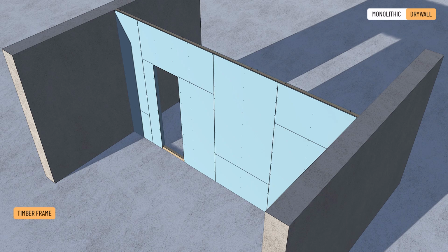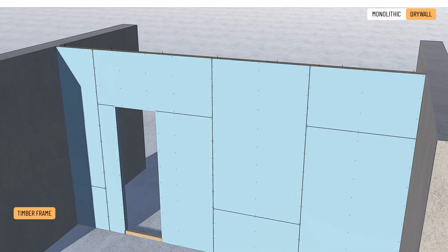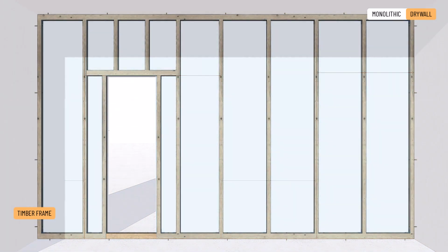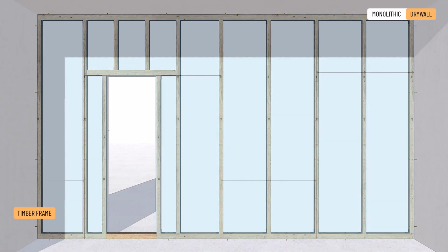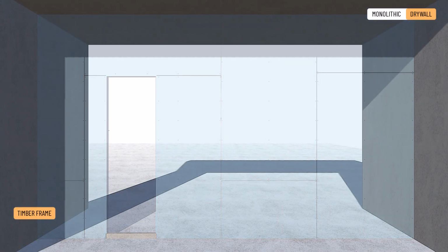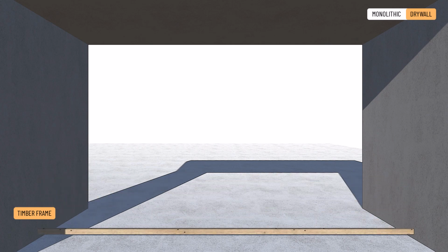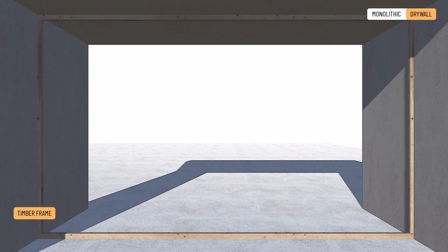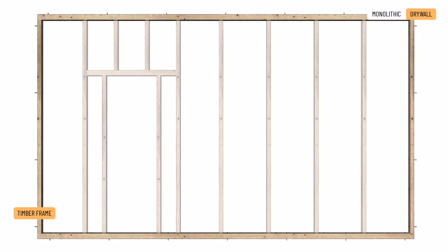Timber frame structure. Today, the more traditional approach to drywall partition walls uses wooden studs for the frame, typically with a 30 by 50 mm profile. Plywood is an alternative to using planed timber. The horizontal plates are typically larger cross-section beams, for example 50 by 50 mm, between which the vertical studs are placed, screwed or nailed.